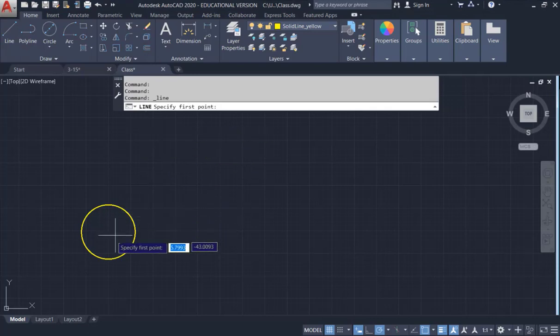If you snap the center point, it will not snap the center. Just a snap is not going to work. What you need to do is hover your mouse on the circle, then move it to the center. Then it will snap the center point.